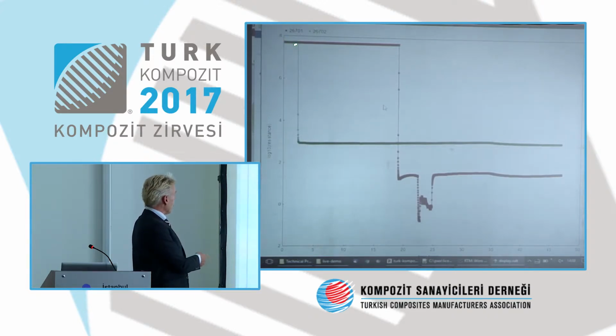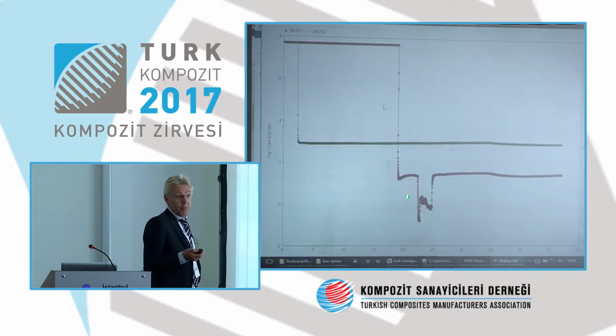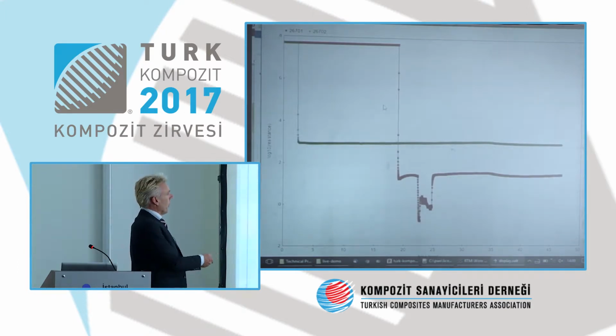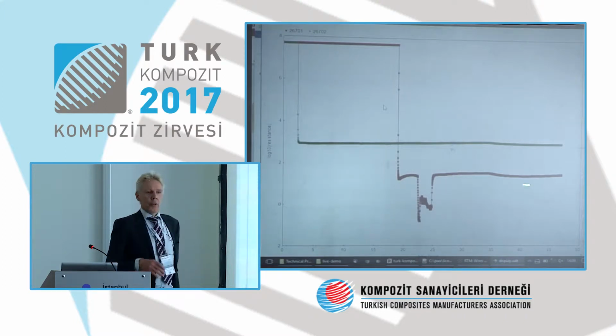So here you have resin, and here you have nothing. This sensor is further away from the inlet. So here you have the resin arrival. Here something weird happened. I don't know what it is, but nobody could explain. Maybe some noise or disturbance, whatever. And then you see the signal develop here. You see the resistance lowering a little bit. This is about half an hour, the time needed for infusion.